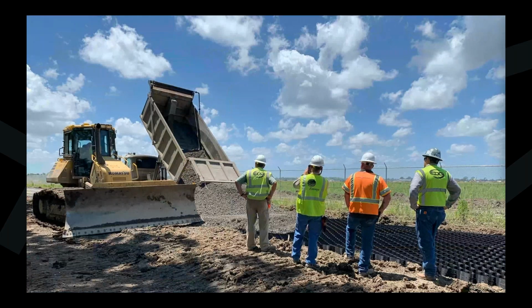And in this case, the infill was simply dumped onto the unfilled panels and then spread out using a bulldozer. So this infill material, like I said, that low quality aggregate sand mix, really saved the owner a significant amount of money because it didn't have to be engineered stone. It didn't have to be trucked in from a faraway location. They were able to use something significantly closer.